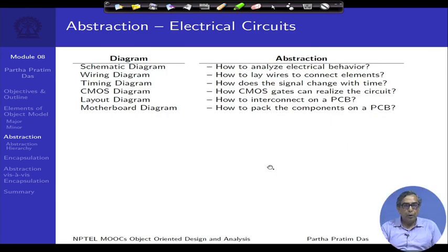So, if we take a look, when do we use a schematic diagram? When we are interested in primarily analyzing the electrical behavior of the circuit. We just want to know how the components are schematically connected without bothering about what kind of wire or what kind of resistor component you are using or what kind of diodes you may be engaging, but you want to use different kinds of electrical analysis models like Kirchhoff's law, Thevenin's theorem, Norton's theorem, superposition and all that, and you engage into a schematic diagram.